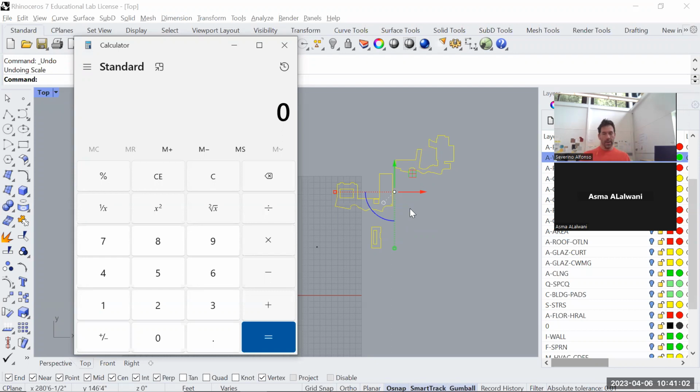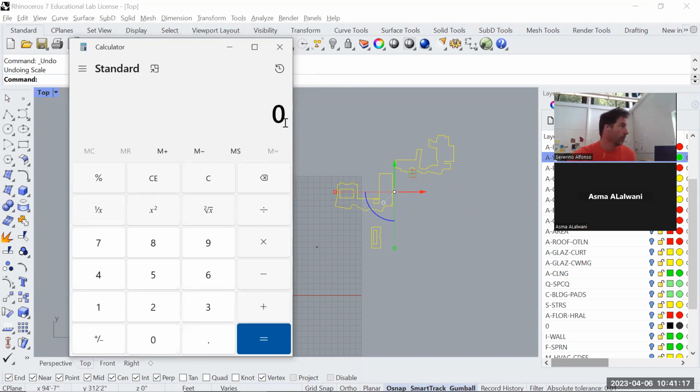Now, it's a good idea, not just suggesting, to print it as if it was a paper space in AutoCAD, making sure things fit nicely, and then come to Rhino or AutoCAD and scale down the drawings to that scale. How will we make the divisions? You just need to know what the scale is. 1 foot equals this, and then you do a division, and you know what to insert when dividing.